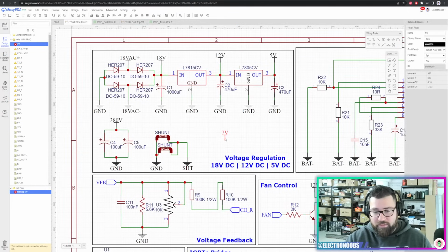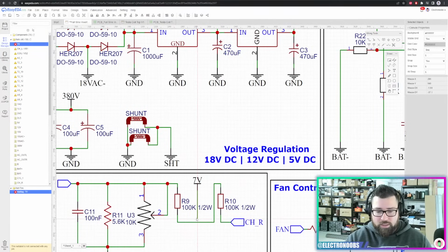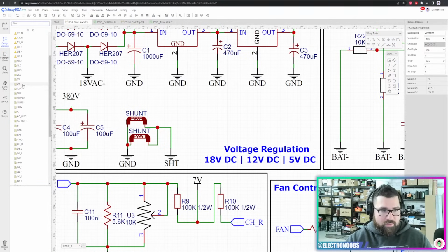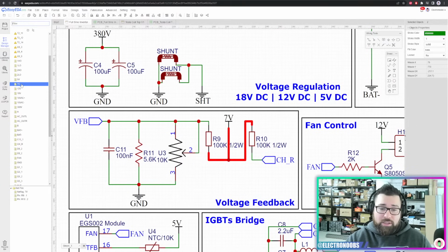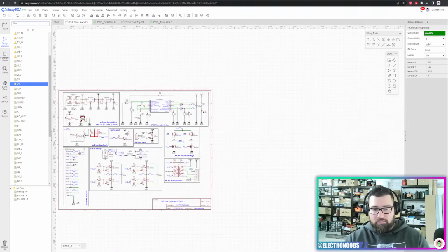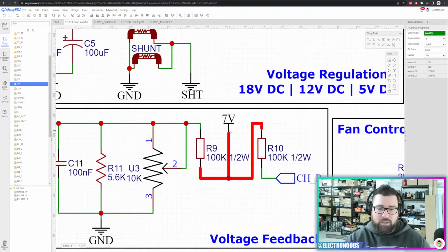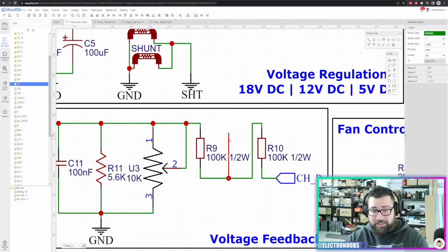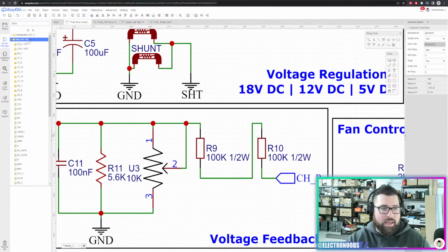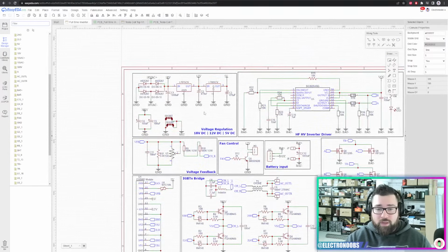But if I take this 7 volts and maybe connect it here, let's just say that I want to connect 7 volts here, I save it and refresh once again. As you can see, the error disappeared and we have the 7 volts net here. And anytime that you click it, depending on your schematic, it will take you there where the connection is. And if I delete it and refresh once again, the 7 volts connection just disappeared. And that's how you can use symbols.